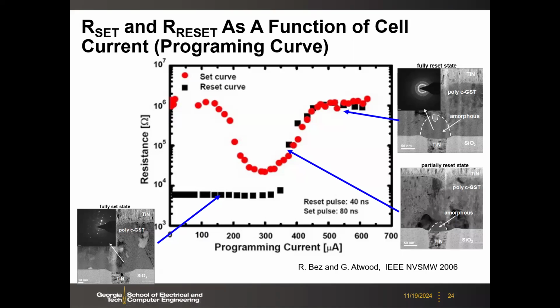So here this is a plug, and then they look at this region, and then they do this electron diffraction. So it has this ordered pattern. That is due to the electrons scattering with the atoms here. So if you have an electron diffraction pattern with these dots, that means this is crystalline phase. The crystal structure is reflected by the electron diffraction.